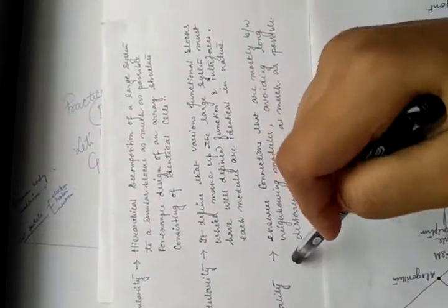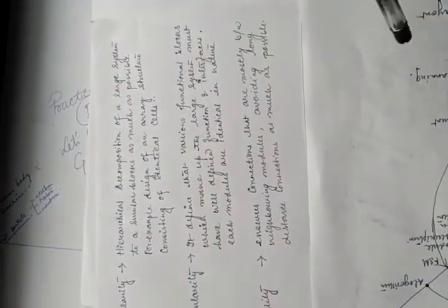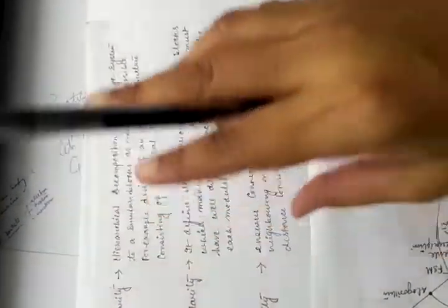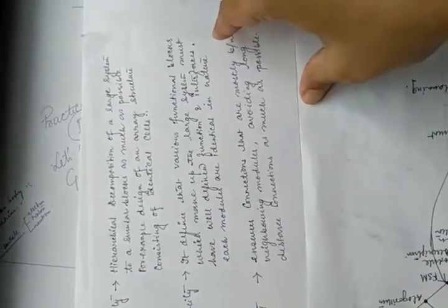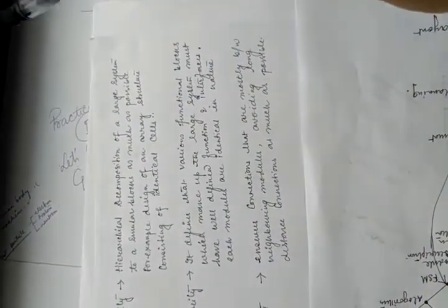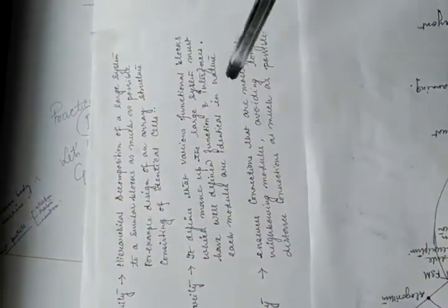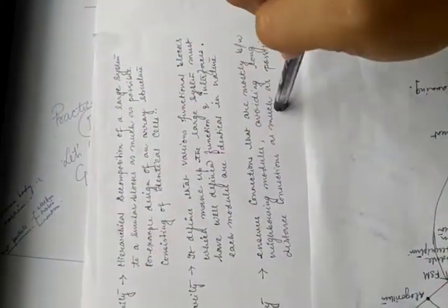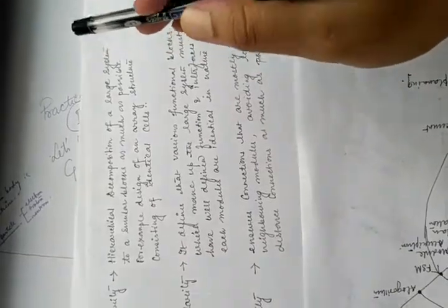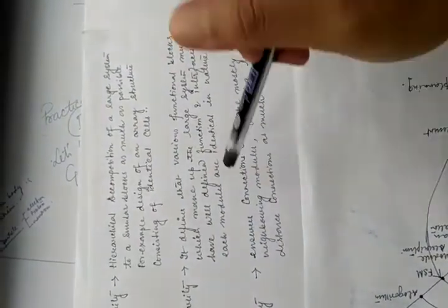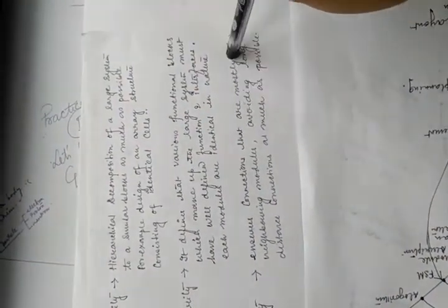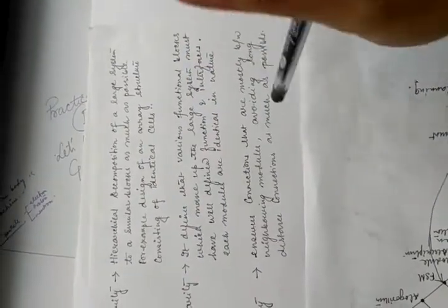And what is locality? Locality, which I mentioned in the previous part: whenever all blocks and modules are placed, we must ensure that they are connected to each other. So ensure that the connections are mostly between neighboring modules. We know the neighboring modules, the module and the module beside it are known as neighboring modules, and avoid long distance connections as much as possible.